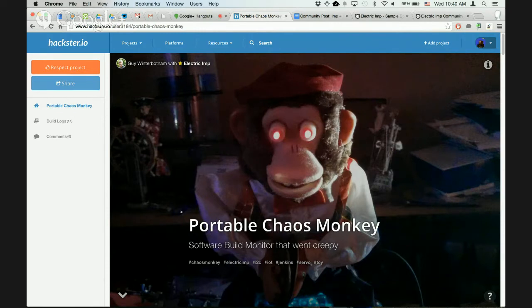If you try to download the frame buffer over UART, it just doesn't work, and that makes people think they're getting the whole image but that it's somehow corrupted, because it displays the little in-browser picture that's been broken in half icon, because it has a JPEG header but the rest of it's missing. So the trick is just to use SPI.